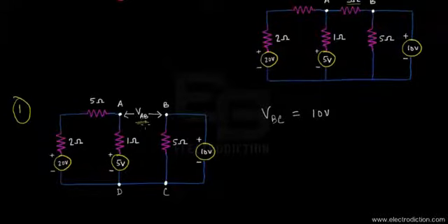There you go. Now we also need to find the voltage difference that would exist across the terminals A and D. It's quite a complex structure over here, so we need to apply KVL in order to find the voltage. Let's assume that there is a current flowing through this left part of the circuit. Let's call it I, or rather I1. That suits it well. Now using this, we can formulate an equation. So let's do that.